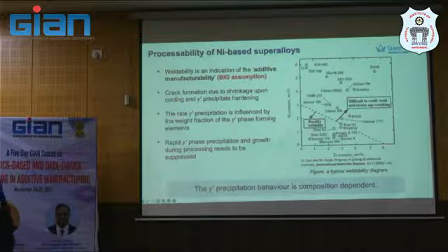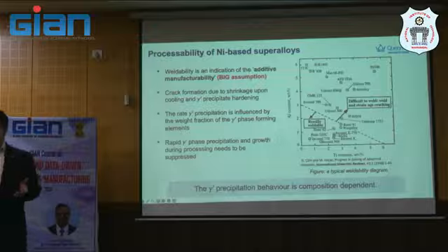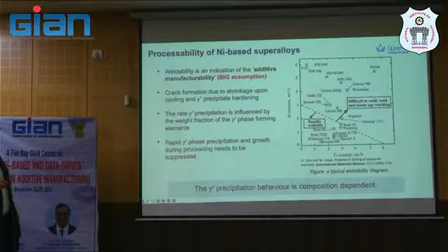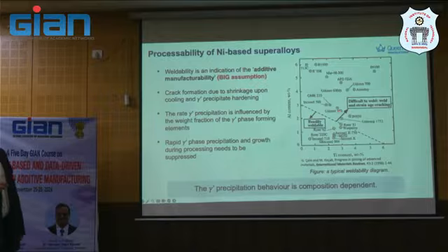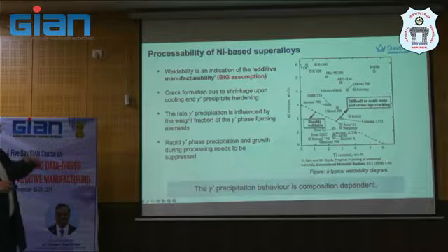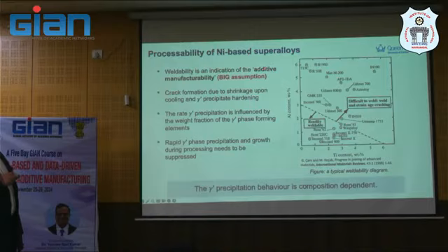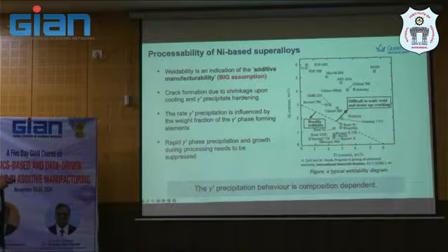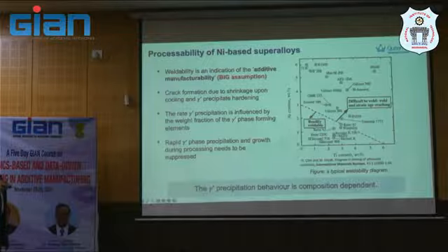So that's what I said yesterday about the Inconel 718. So we start from what we have, and then based on what we have, we believe in the weldability diagram, but we know that it doesn't have anything to do with additive manufacturing. But we borrow this concept and we assume that this additive manufacturability is actually similar, I would say, to weldability, and this is a big assumption. That's why we follow this kind of diagram to develop some indices for the crack.